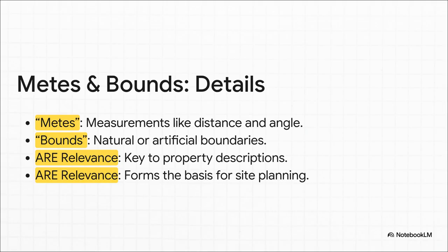Because you are going to be looking at legal property documents, you're going to be looking at surveys, and understanding a meets and bounds description is how you actually confirm those property lines. And here's the bottom line. You cannot create a valid site plan if you don't understand this legal description first. It is literally the foundation for everything else.